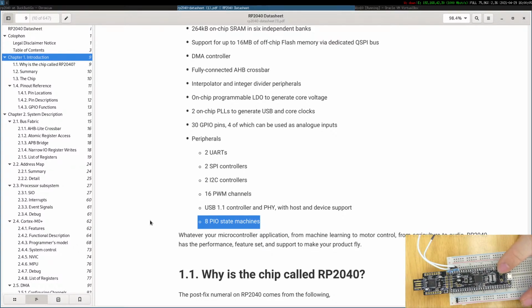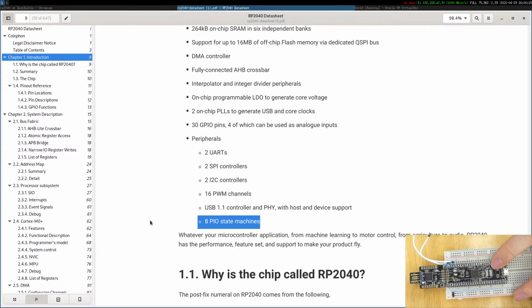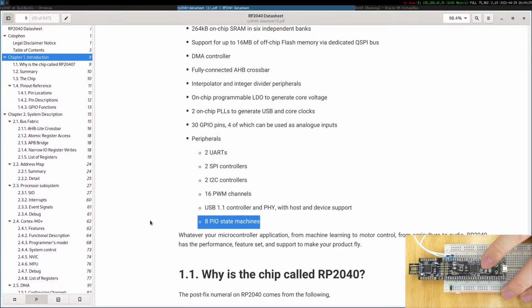I need one microcontroller, I need one UART, one SPI. Probably I could also program one of these blocks to do JTAG or SWD if I don't repurpose SPI. I would have one timer to measure the frequency, but I think that's pretty sufficient. The 24 blocks inside here are pretty sufficient. But if you want like 8 UARTs, I'm not sure that this is good enough and it has enough